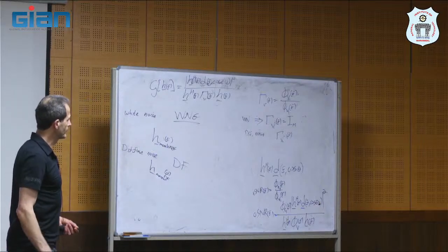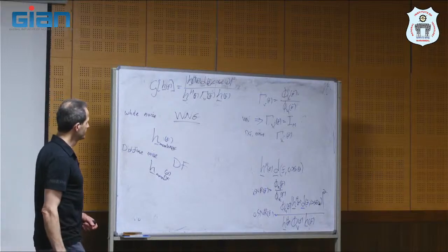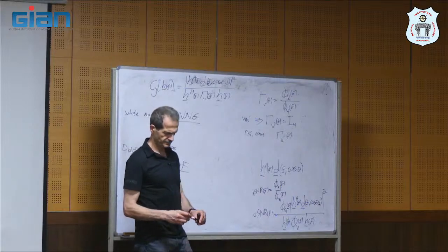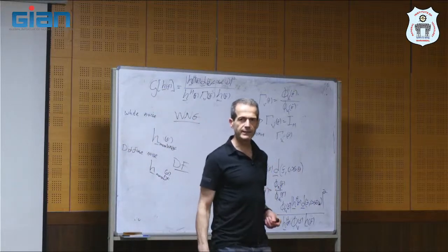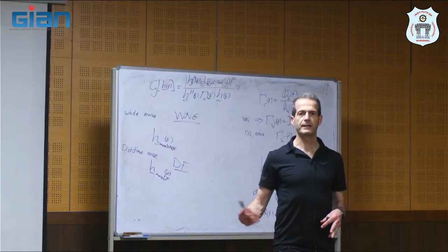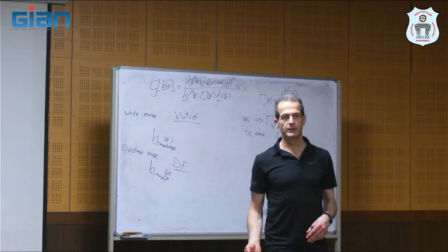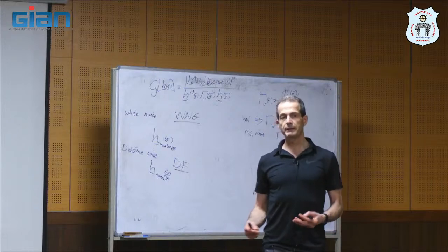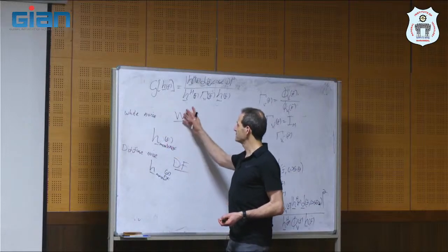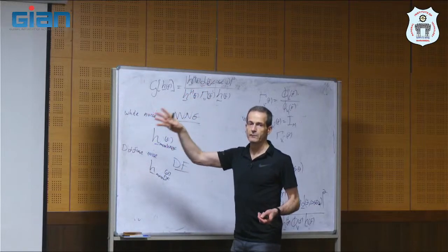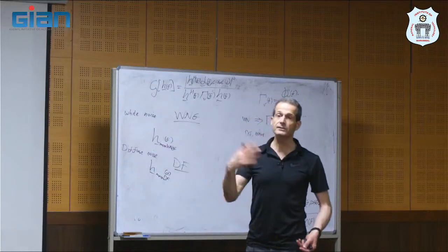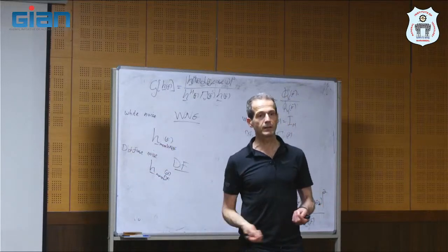Okay? So we will show something that is very interesting. You can say, why do we assume that we have spatially white noise, thermal noise? Maybe we can find a beamformer that maximizes the gain both for spatially white noise and diffuse noise and other types of noise, so it will be optimal.